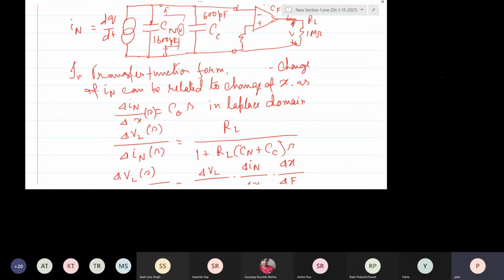And because we cannot measure that charge difference directly, the measurement circuit, which has been given in the books of Bentley and is usually used, is that we have a cable and then a charge amplifier, which is converting this current through an integrator to a voltage, and this load resistance is a voltmeter equivalent.